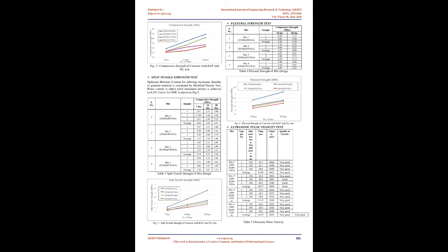Thereafter the concrete mix is tested for slump value, compressive strength, split tensile and flexural strength after creating the design mix of concrete, in place of virgin aggregates, with 20% RAP material and fly ash in proportions of 0%, 5%, 10% and 15% respectively.